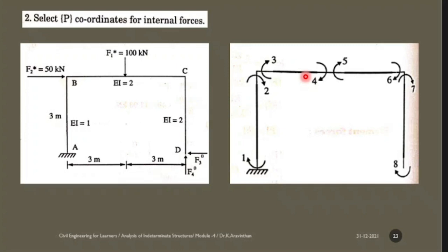But now currently you are having how many elements here? 4 elements. That means your matrix size will be how much? 8 by 8 matrix. So you will be having 8 number of rows and 8 number of columns. So before starting your sum, you can understand what is the size of your problem, and with the number of elements you can find the number of the nodes.